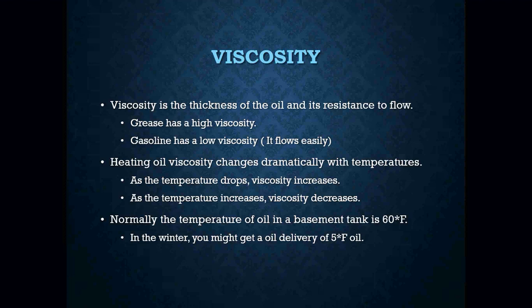So viscosity is the thickness of the oil and its resistance to flow. Grease has a high viscosity. Gasoline has a low viscosity. Why? Because think about it, it flows easy. Okay? Heating oil viscosity is going to change depending on the temperature that it's in. So when we're thinking about viscosity, we have to remember as the temperature drops outside, the viscosity is going to increase. It's going to thicken up. And as it warms up, the viscosity is going to decrease. It's going to loosen up. It's going to become more like a liquid.